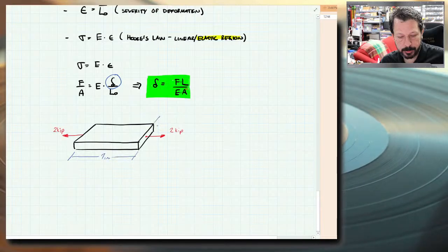Let's make it not 1 inch thick because I want it to actually have a chance of being relatively thin. Let's make it a 1/4 inch thick. And let's make it, I don't have a good place to put this dimension, make it 2 inches this way. All right, and let's make it out of our structural steel.